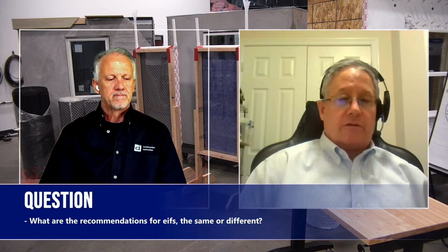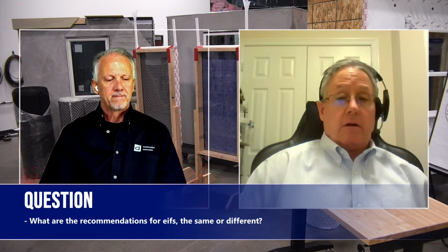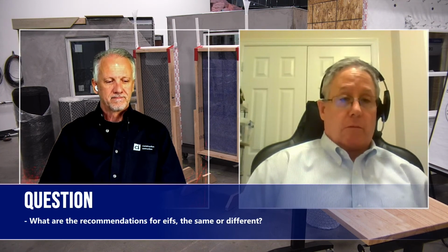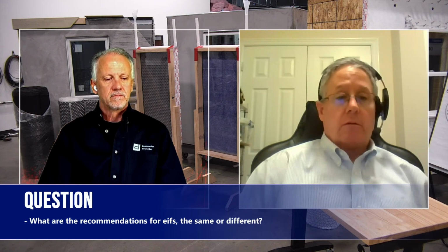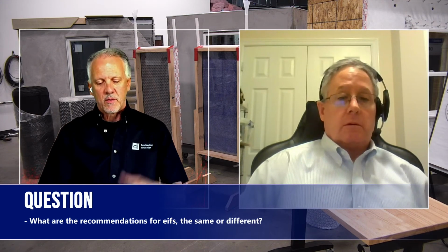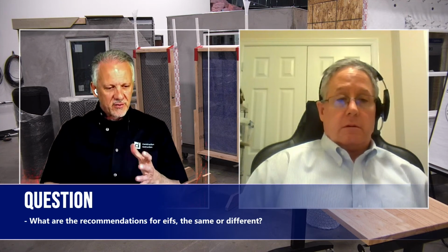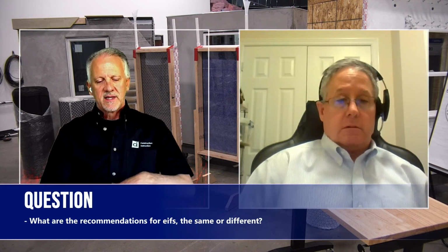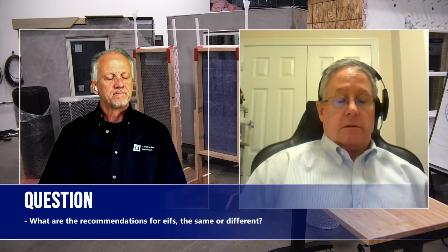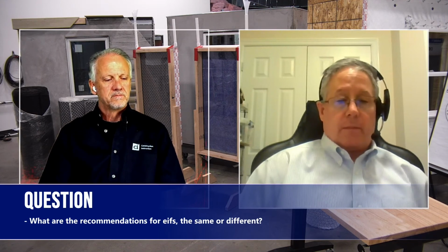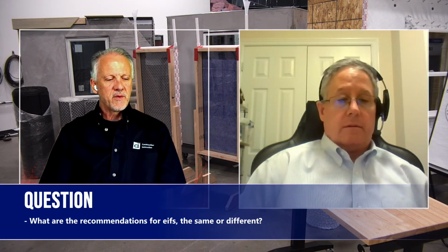Yeah, EIFS generally have a proprietary water resistant barrier and drainage function to them that are required in order to meet their warranty requirements. That's correct. Yeah. Well, oftentimes, weather barrier, and sometimes the foam on the backside is grooved to provide drainage. There's a liquid applied and mechanically attached as well. Yeah. And we are seeing a few more EIFS applications.